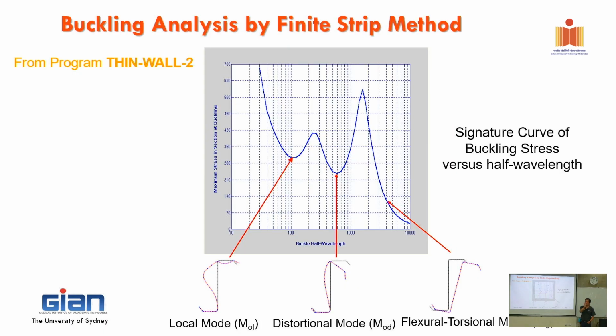So the effective width that you're asking about, is that actually the ultimate strength already, because we take into account the post buckling, because it's working out to be effective. So that is post buckling. Remember the first one that we ran through, the stress is distributed, so that is post buckling. It's a little bit higher than the critical stress.